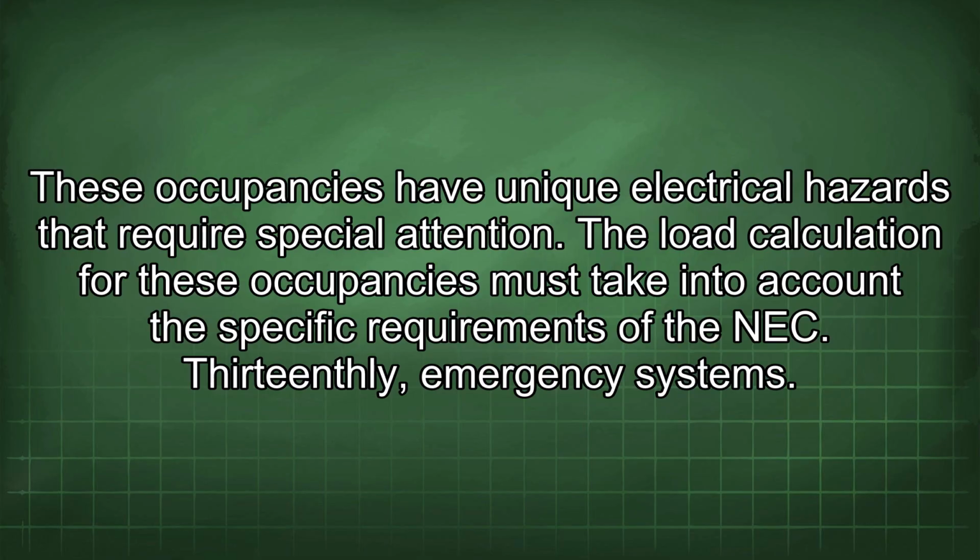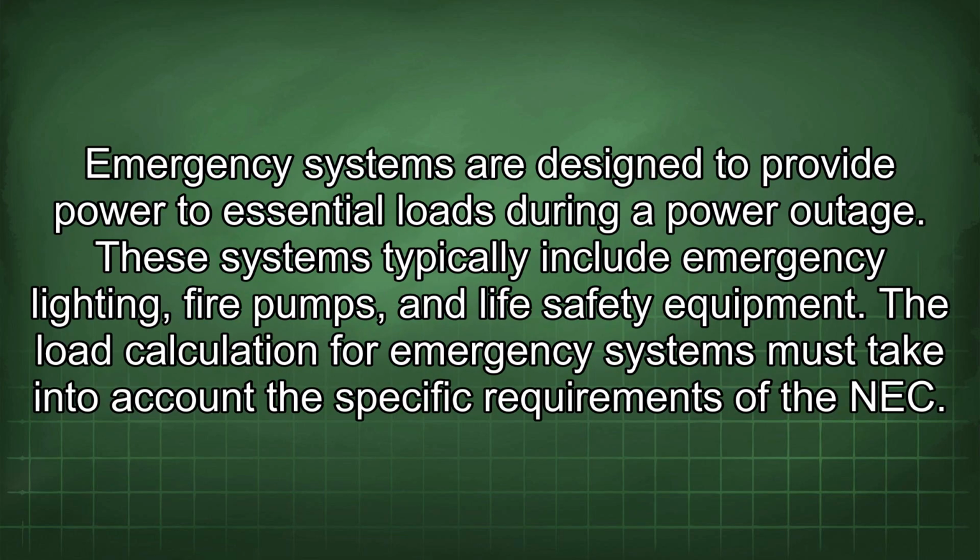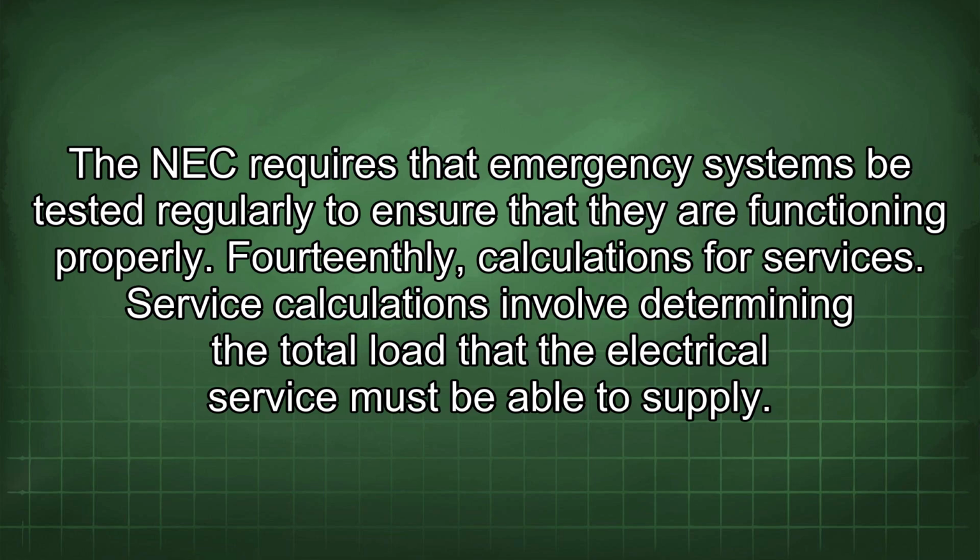13th, emergency systems. Emergency systems are designed to provide power to essential loads during a power outage. These systems typically include emergency lighting, fire pumps, and life safety equipment. The load calculation for emergency systems must take into account the specific requirements of the NEC. The NEC requires that emergency systems be tested regularly to ensure that they are functioning properly.